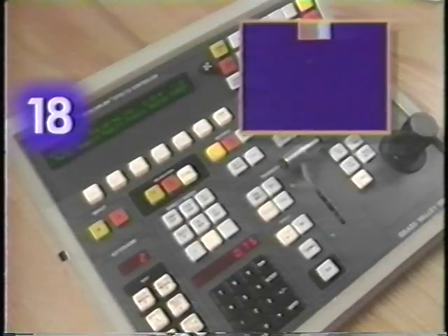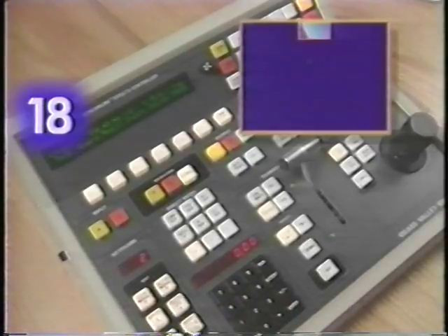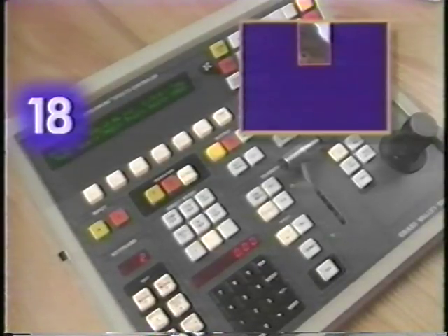It's important to remember that when you're performing an orbit, the picture may move off-screen. If it does move and you can't find it, select Locate Size. Then to bring the picture back on screen, press X, 0, Enter, and Y, 0, Enter. This will set the X and Y values of the location parameter to 0.